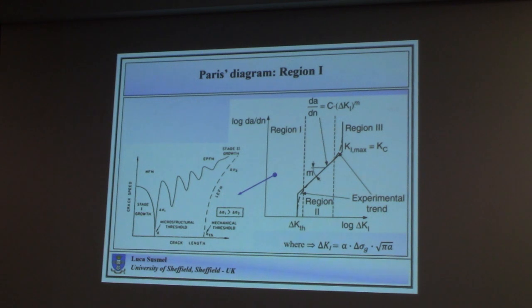You know? What engineers do when it comes to real components is every now and then inspecting real structures, and they see a crack, and the calculation they do is to check if they are still in this region. If they are still in this region, they say, okay, I know that the crack is there, we'll keep monitoring it.